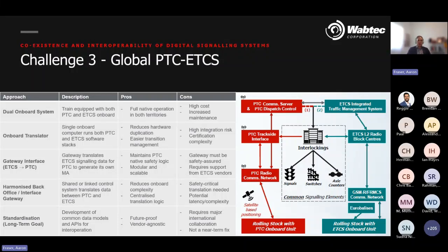So when considering how to achieve interoperability between I-ETMS and ETCS, there are several technical pathways, some of which are shown as examples on this slide, each with different trade-offs. Some of these options have already been explored in previous studies undertaken by Sydney Trains and ARTC for ATMS to ETCS interoperability. So I've listed some of those options on this slide, but for the sake of simplicity and without touching on any commercial sensitivities, it really boils down to one, do you want to retain line-side signals similar to what we observed in Canada? Probably the answer to that is no. It's costly. You're going to have to maintain those signals for the lifetime of the asset.